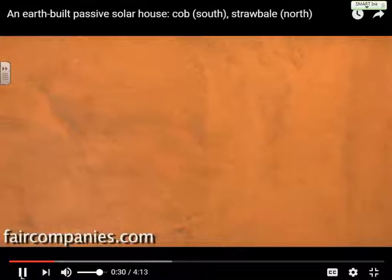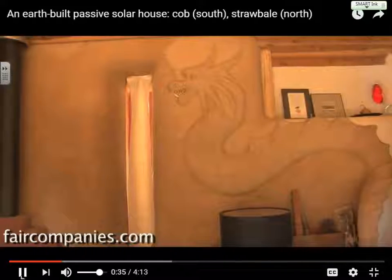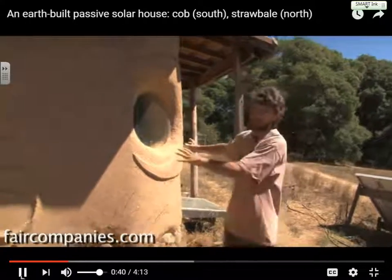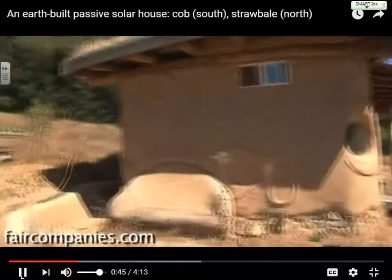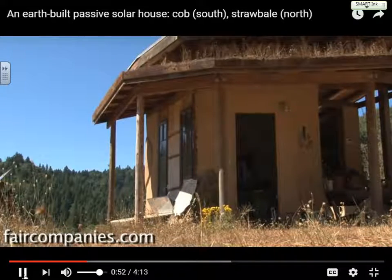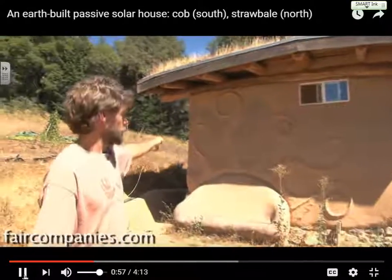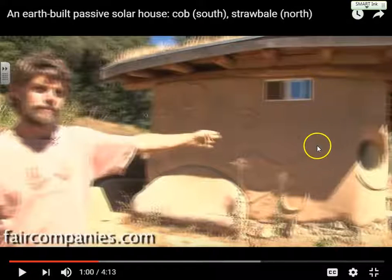Thermal mass, like earth, is a completely critical part of an effective passive solar design. This is designed as a passive solar structure, so the thermal mass of the cob is on the south side of the building where the sun hits. You can't build a good passive solar house out of 2x4s and sheetrock and styrofoam insulation because you don't have the mass. So this is actually a hybrid structure. The back, the part to the left of this wall, is straw bale, and the part to the right is cob. So in case you missed it, this front part is called cob, C-O-B, and that's a good thermal mass.